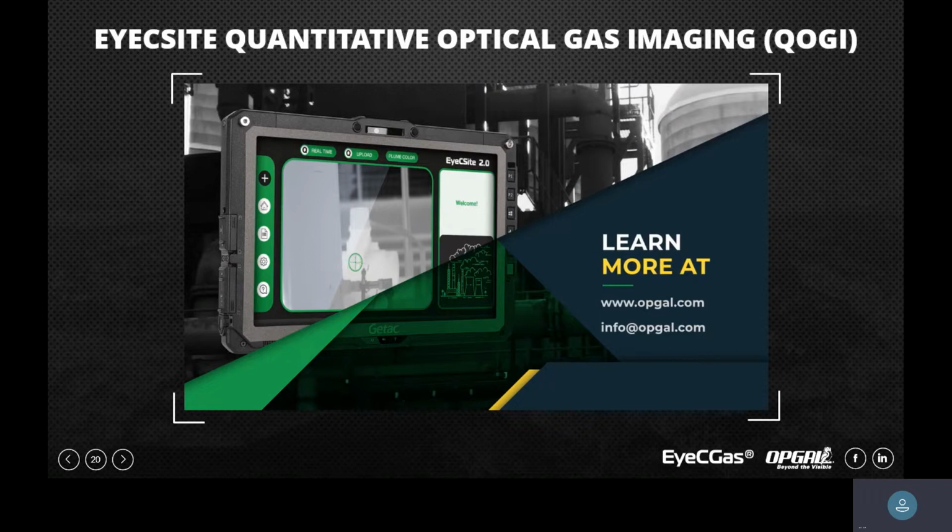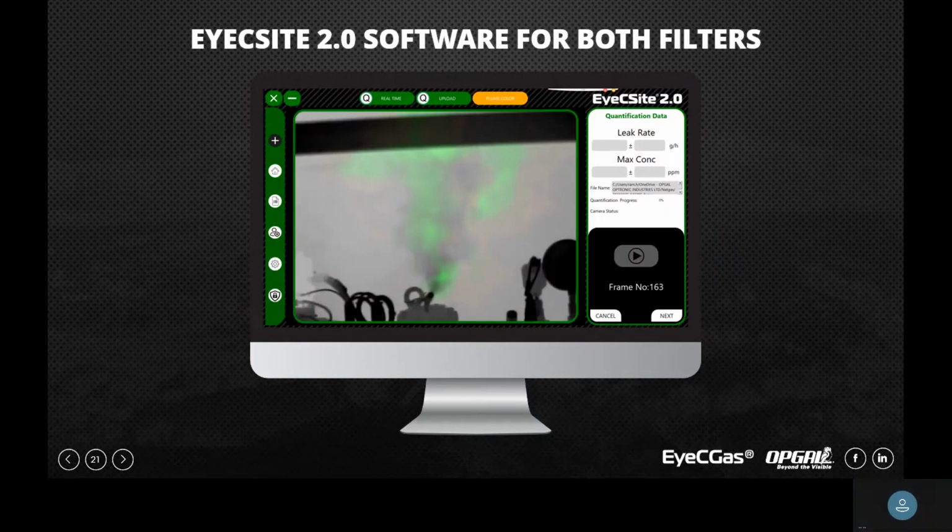So we can better quantify small leaks in worse environmental conditions only by flipping the filter. Right now we have the factors only for the standard filter, but we can add the calibration curves, not factors, curves, into this once you replace your filter.